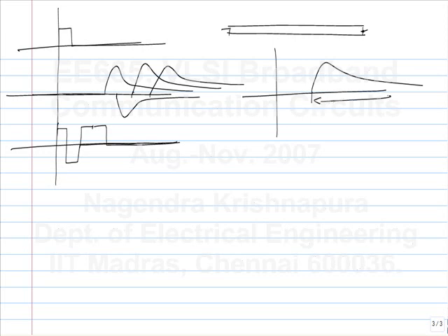After, let's say, 10 bits, there is still some residue remaining. If I transmit a bit now, firstly there is this delay TD, and then let's say this is 10 times TS. After TD plus 10 TS, I can still see the effect of this bit. There is nothing wrong with that, right?